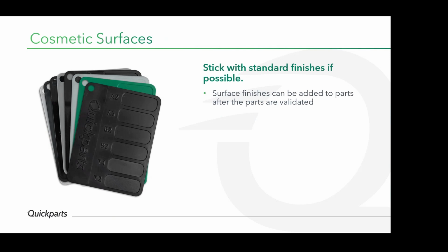Again, cosmetic surfaces, I think we have discussed that earlier, but use standard surface finishes. That helps, so it keeps your cost down. And again, if you choose very high cosmetics, then maybe the chances of rejection are more, right? When it is inspected, oh, there is some mark somewhere that your quality will reject.